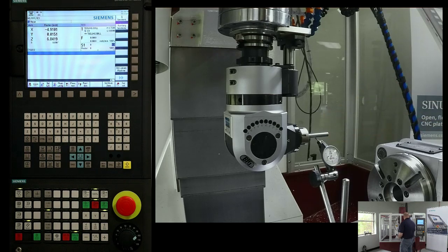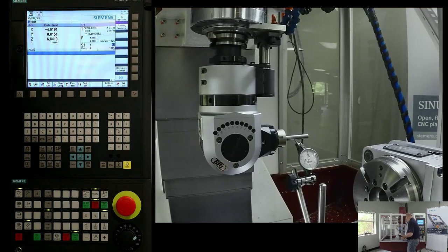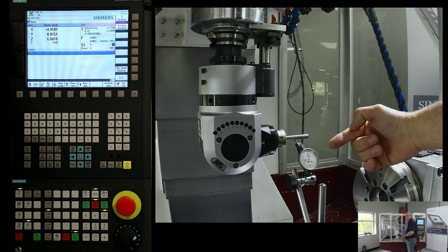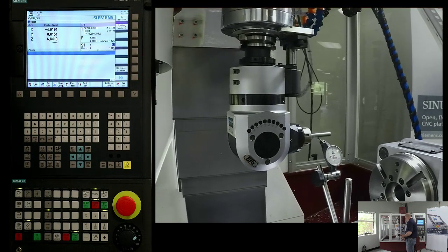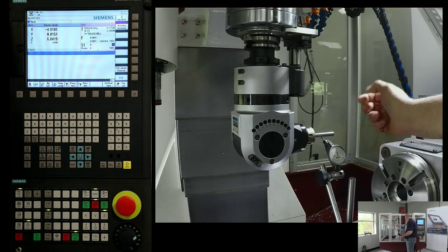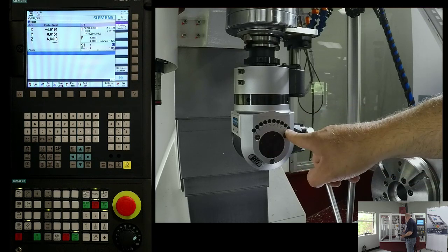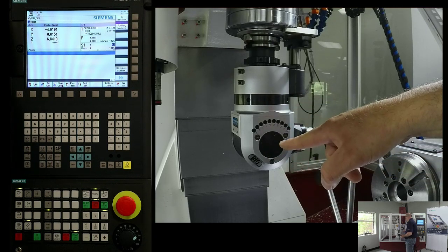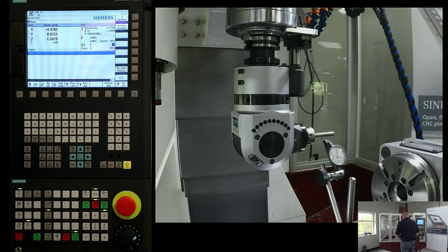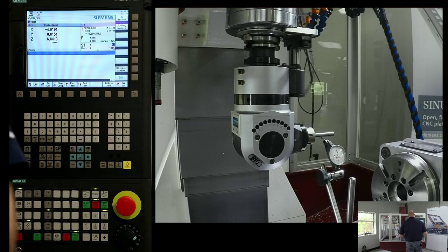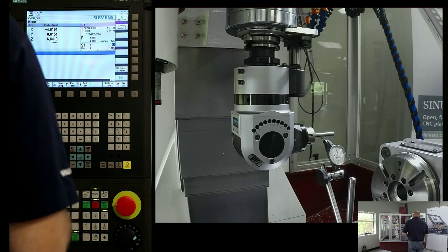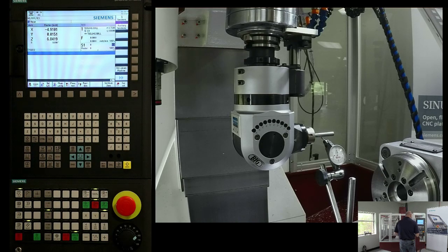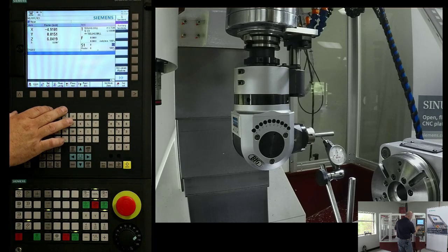So here, if you look, I'm sitting at a 0 point, all right? We'll bring the indicator over a little bit, or the camera. I'm sitting at a 0 point on my spindle, and basically I'm off center line of this axis. This axis is sitting at 0 degrees, or full 90. So I'm off center line by the radius of this dowel pin. This dowel pin, or this ground rod, is 3/8 of an inch. So that's 3/16 or .1875 off. So what I want to do is set a temporary 0 there.